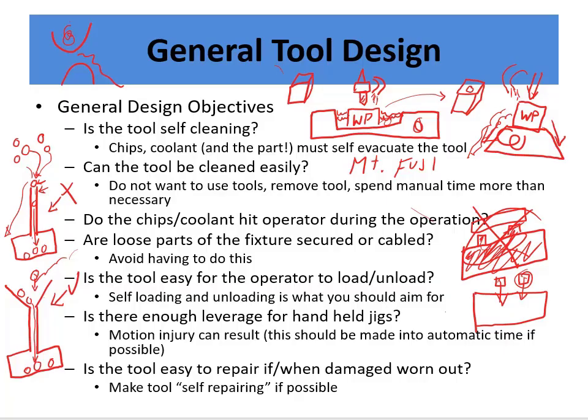It's not easy to do, but there are certain situations where you can do it. You can have things where a locating clamp is designed so that as it wears, it doesn't matter how much it wears, it will still be able to clamp. Sometimes if you have a clamp set up with a very limited stroke length, when the end effector attached to that stroke gets worn, the stroke can't extend any further to clamp, and you maybe have loose parts.